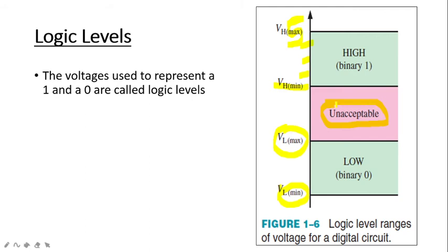Now giving it in numerical terms, observe this or write it down. See, for an example, consider that the high input values vary for a certain type of digital circuit. We will see that the high input may vary from 2 to 3.3 volts and the low input may range from 0 to 0.8 volts. Understood?